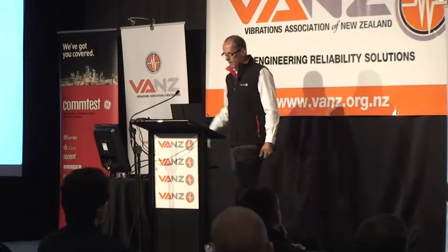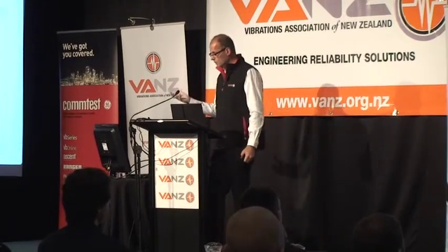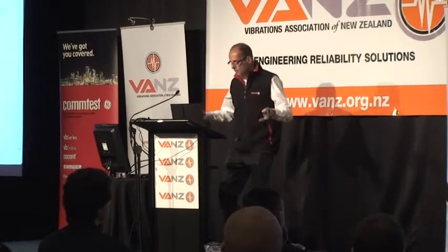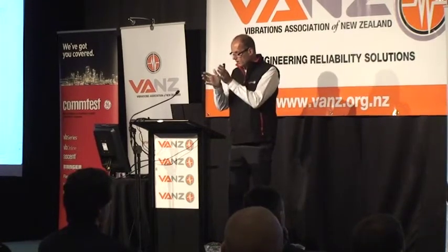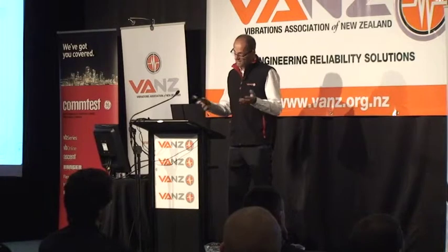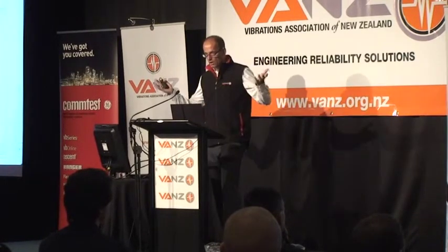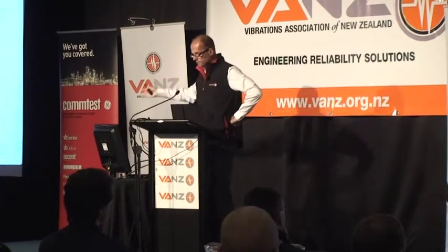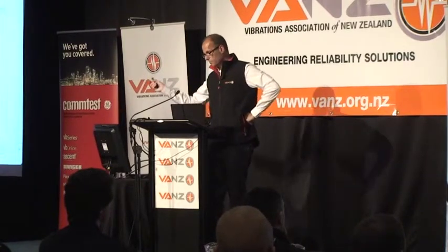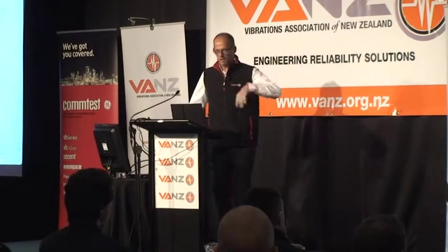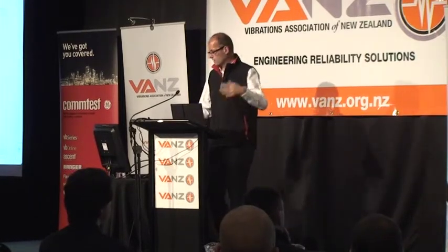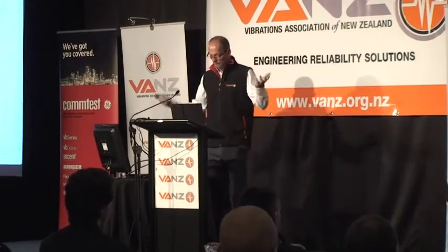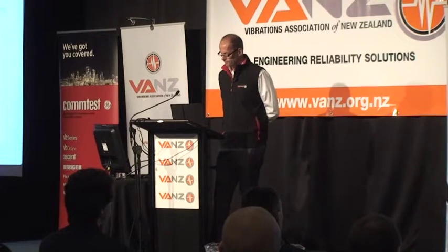So this could have come about for a couple of reasons, but the most likely reason is something called false Brinelling. So you've got a pump sitting in standby and it's vibrating the whole time. It's not operating, just vibrating. And the rollers are chipping away at that inner race and the outer race. We run the machine and lo and behold, we get this fault condition. So if you do nothing, then this is just going to happen again. We'll be replacing the bearing again. And how many times have you seen in the plant, "Oh, that machine, yeah, we have to replace the bearing quite frequently." Yeah, but why? And of course, there are other reasons for bearing faults, and you have to understand what's going on.